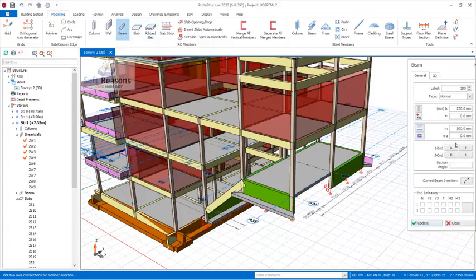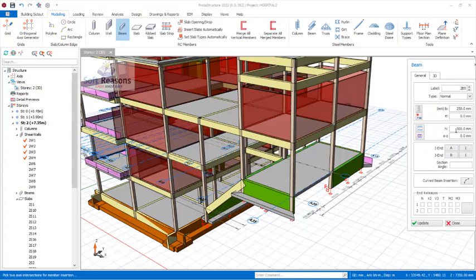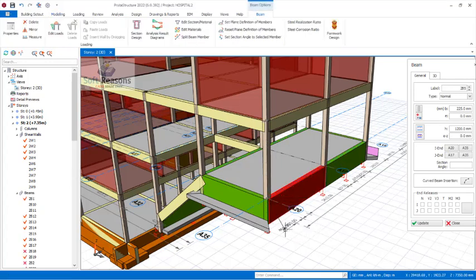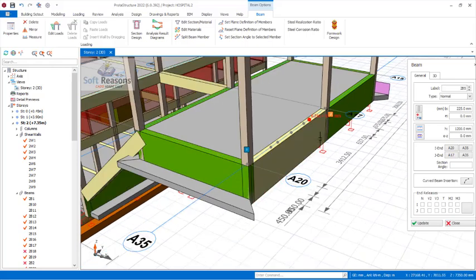All right, so once you click on beam, what you are having is your beam depth. In this case, you wouldn't have to go into setting anything like support. So we wouldn't want to set any support in a beam system. What you just have to do is to extend this beam depth. For instance, let's say we have it to be 1200 right there, and then the thickness of the beam is going to be 225, just like this. After which we come over to this point, pick that point, and over to this side and pick that. Once you pick the two sides, you can now see the beam is properly placed successfully right there. So you don't need to do all those necessary settings if you want to use a beam.